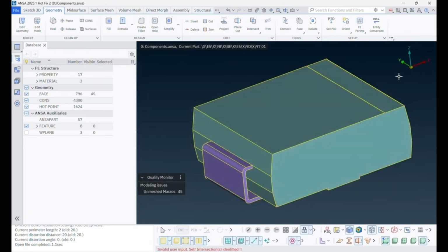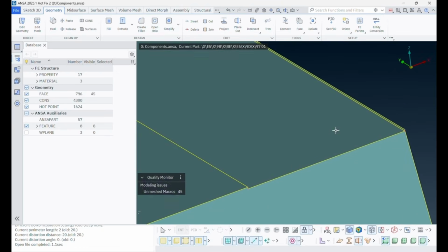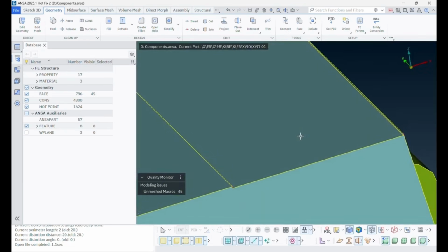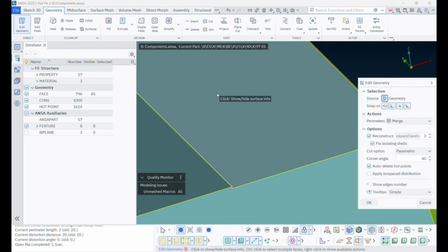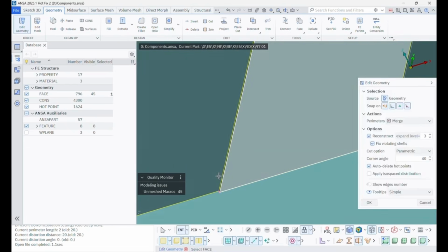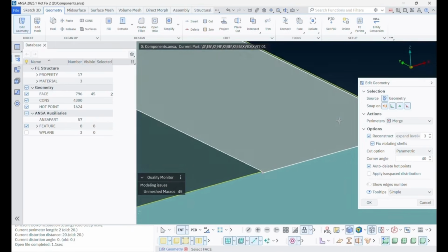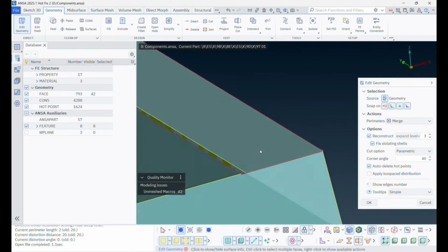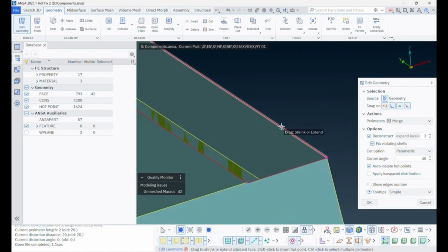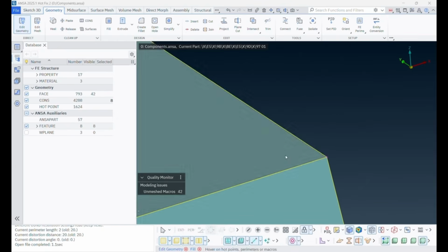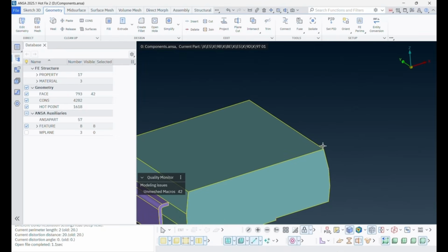If geometry adjustment is needed after removing the logo, for example to flatten a surface, you can delete and recreate the faces. An efficient approach is to use Select Multiple in Direct Edit to select the relevant faces, then execute delete. Then use Fill from the right-click menu to rebuild the region. The resulting surfaces are usually cleaner and more suitable for subsequent mapping and solid mesh generation.